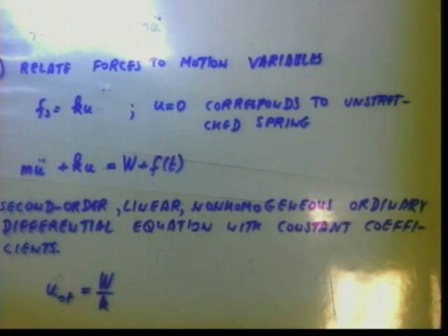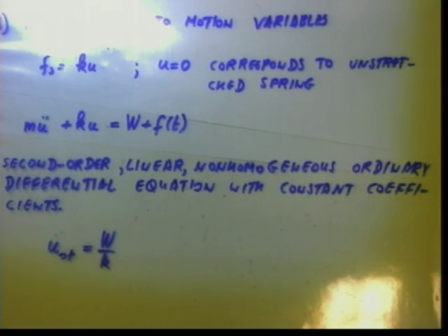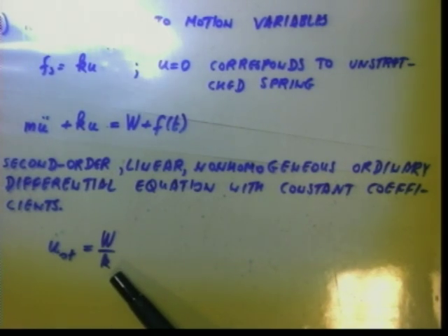Okay, now this equation is a dynamic equation, but it is also always interesting to relate it to static behavior. Now, what is static behavior? Static behavior is behavior when time is not involved. If I had just the weight of the mass acting on the spring, forget now additional loads, just weight, then there will be a displacement, which is weight divided by k.